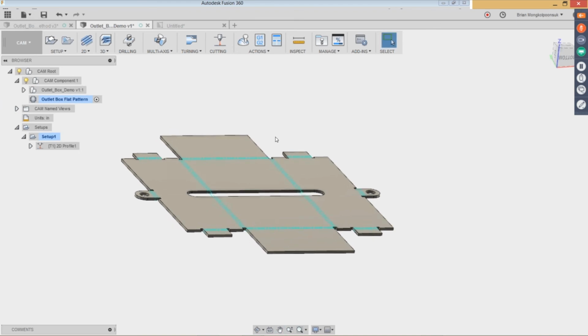Yeah, so that has to do with the Fusion 360 CAD CAM integration. So whatever you do to the CAD environment, it's the same data. So this is essentially the CAD data that you see here on the screen. And so if I, for instance, make this flange a little bit longer, it will come in here. It'll tell us to update it. But once you update it, then we can update the tool paths as well, and then it's pretty much good to go from there. If that answers your question. Yep. Looks like it does.